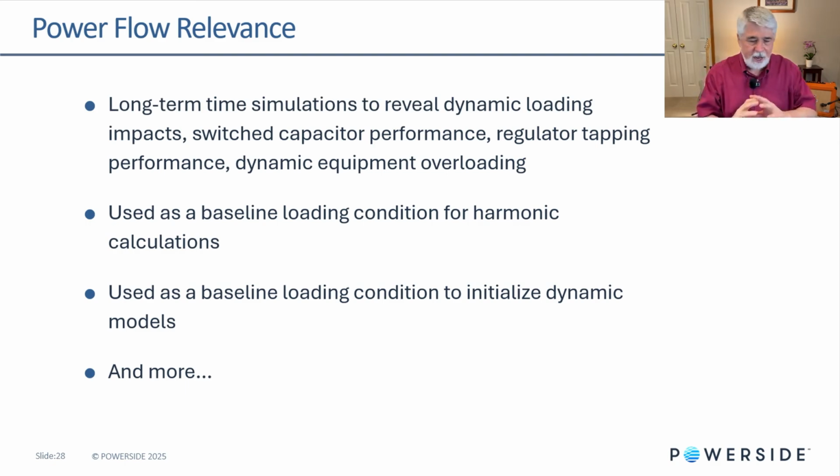So consider you have a distribution feeder, and you simulate a power flow that represents this loading condition, and then you simulate another one for 5 minutes later, and then 5 minutes later. So it's a series of power flow simulations over a day that can help you determine how dynamic changes in loading are affecting switched capacitor performance, coming on, going off, coming on, going off, regulator tapping performance, and then the dynamic loading on your equipment.